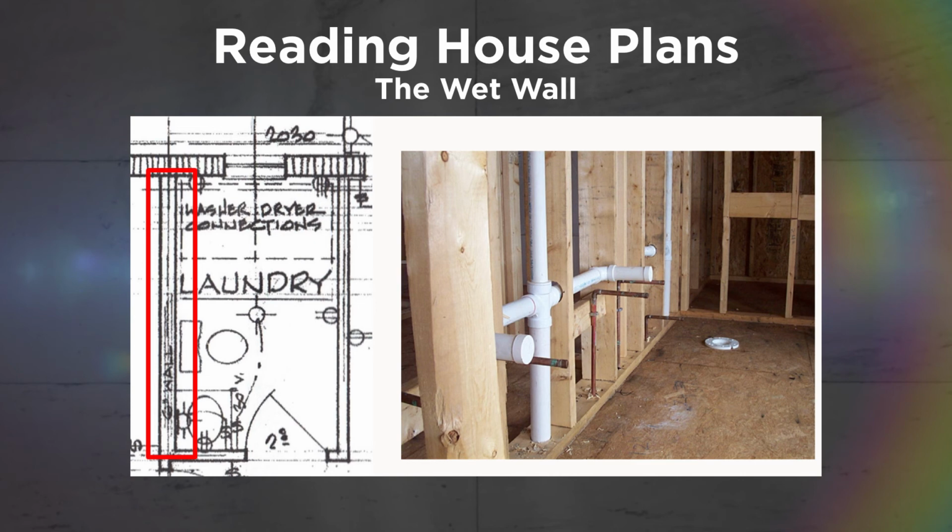Since a 2x4 stud is actually less than a perfect 4 inches, the 4-inch stack wouldn't fit in a standard stud wall. Therefore, a 2x6 wall is constructed in some areas of the home. It's not a coincidence that the vanity, toilet, and washing machine are in the left side of the bathroom. All of these appliances and fixtures use water.